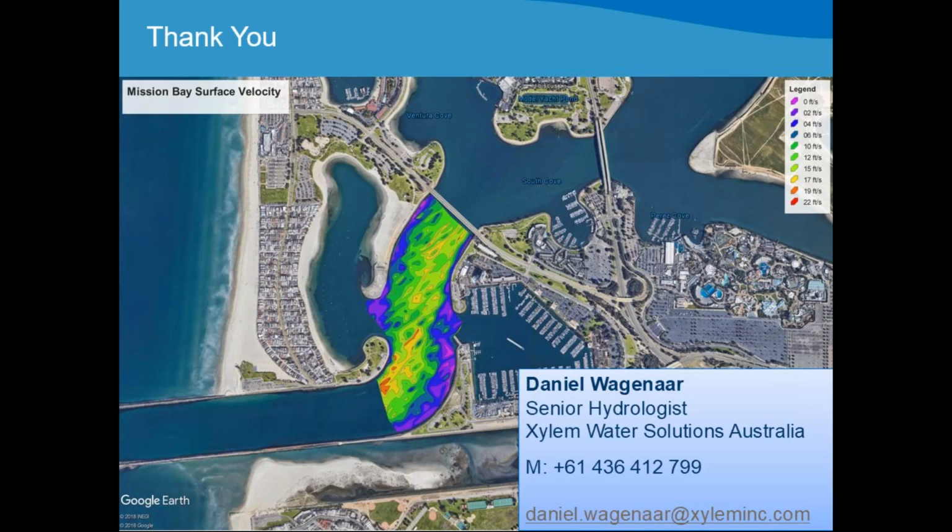No, the 16 centimeter blanking distance should be sufficient for that. Although saying that, from all the research papers, irrespective of what instrument you're using, if you're using TRDI or SonTek or Nortek, the instrument itself has an impact on the flow patterns around the instrument and below it, as well as the platform you're using. And something that I didn't mention is the approach velocity, and will they have an impact on that as well? I think in those circumstances, what I would do is analyze the velocity profiles in Extrap or QRev